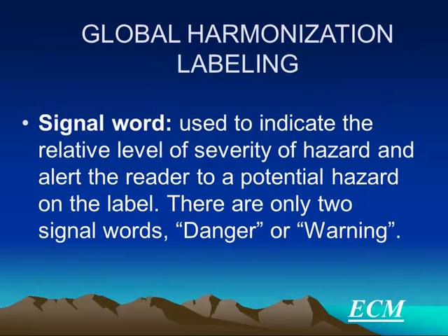Okay, the next thing that's on there has to be a signal word. There's only two words that are a signal word. It's either danger or warning. So in the example I was given before, the one that might just be corrosive to a drum would be warning, and then the one I was saying, the hydrofluoric acid, if you get it on yourself, you're in bad shape. That's going to be a danger. So it kind of gives you a sense of what the level of hazard of the container is.